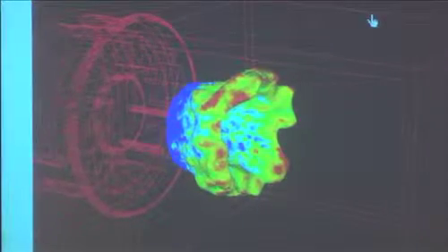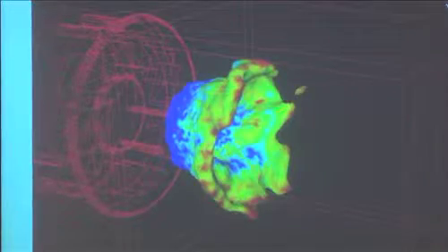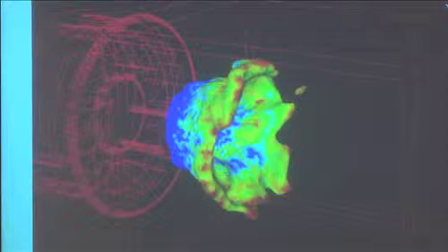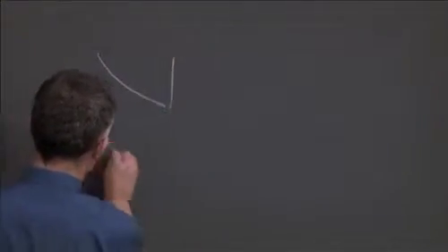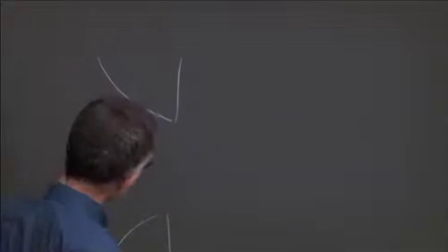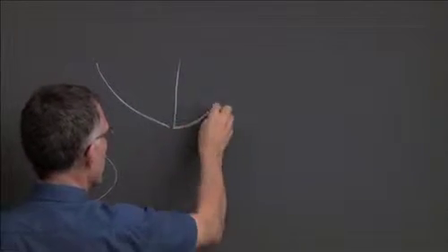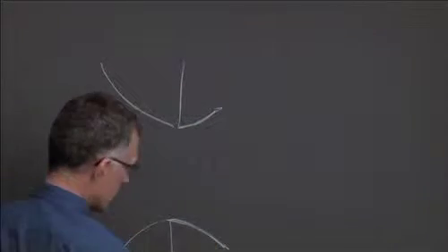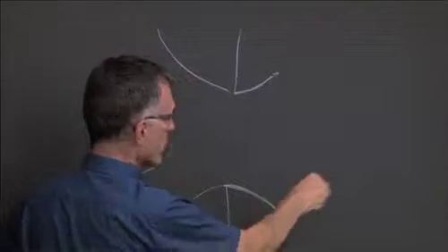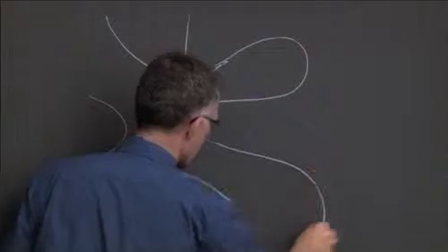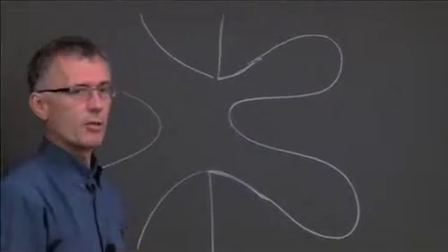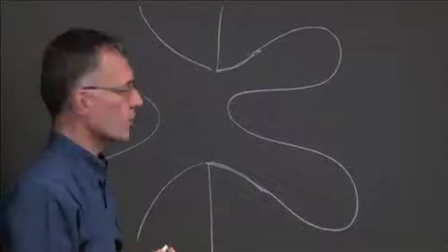Now you ignite this thing. Okay, you have to get your 3D goggles to understand there. The shape of these flames in swirl flows is very specific. Okay, the flames almost always look the same. If you have a swirler like this with a wall here, a hub, here there is a recirculation zone, so the flame will be stabilized here and here. And in addition to that, there is a recirculation zone here also. So what you see as a shape is something like this. Okay, that will be the typical shape in most swirl combustors.